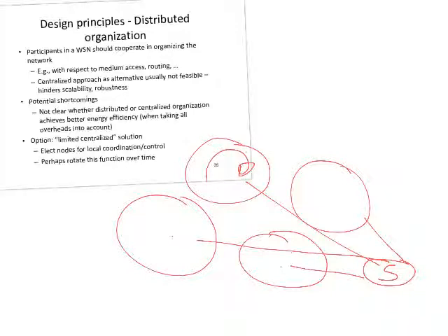At the same time, we can be as scalable as we want to be, because the number of sensors in each cluster is going to be limited, right? We can have as many clusters as we want. Ideally, we would want to have one big cluster to simplify the problem of organizing the nodes or the duty cycles for energy efficiency. But that's not possible. So we can have a limited number of sensors per cluster to perform this optimization locally, and then send some aggregate decisions to the sink node.